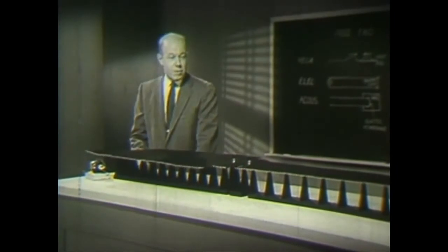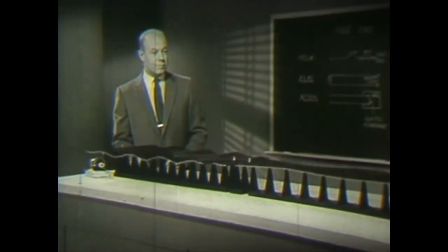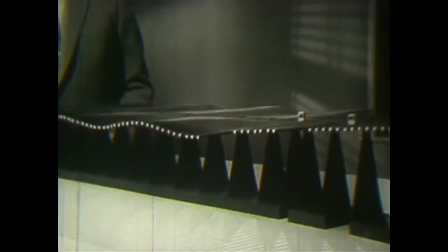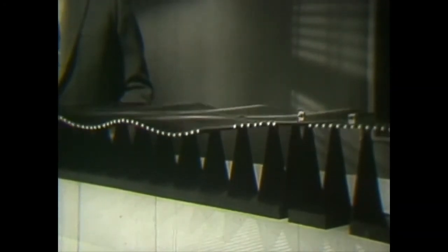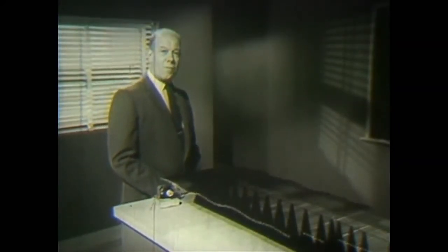I'll sandwich it in here and then show you how it operates to promote the transmission of wave energy across this discontinuity without reflection loss. All right, here come the waves, and now you watch what happens. And there they go. There is no perceptible partial standing wave on the input portion of this transmission system, as there would be if reflections were coming back from the junction. Apparently, then, I have matched the impedances of these two machines.